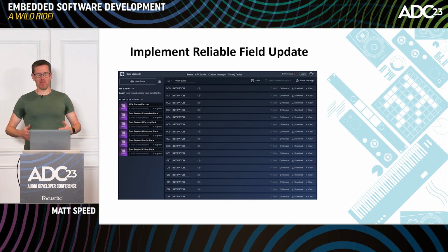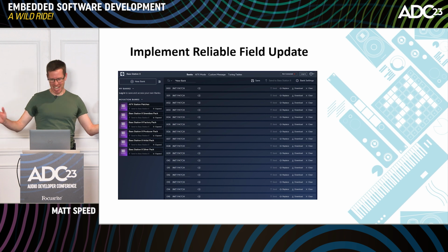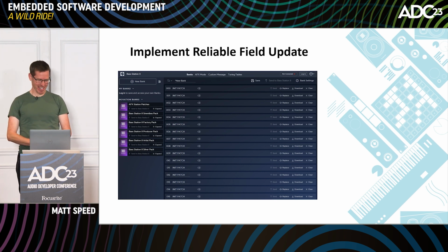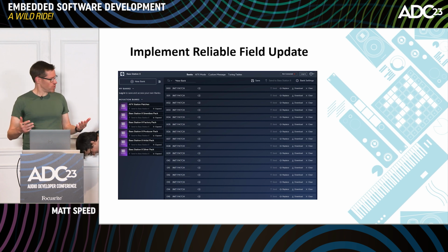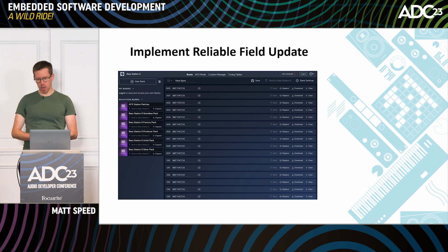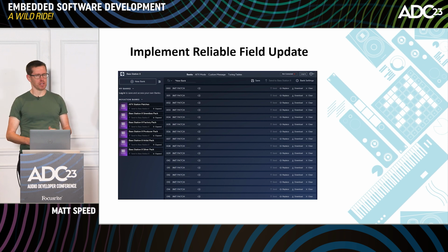My opinion of a bootloader is that it's the scariest thing that a firmware engineer will ever develop. And for running firmware upgrades, it's essential. We want to get it running as soon as possible. We'll often use it during development. It's nice to do a bit of dog fooding with the firmware upgrader and make sure it gets as many flying hours as possible.